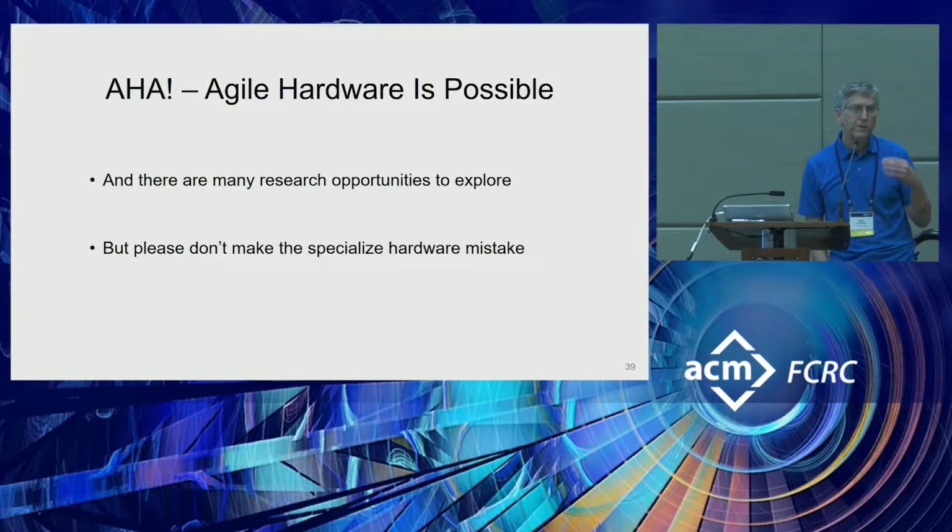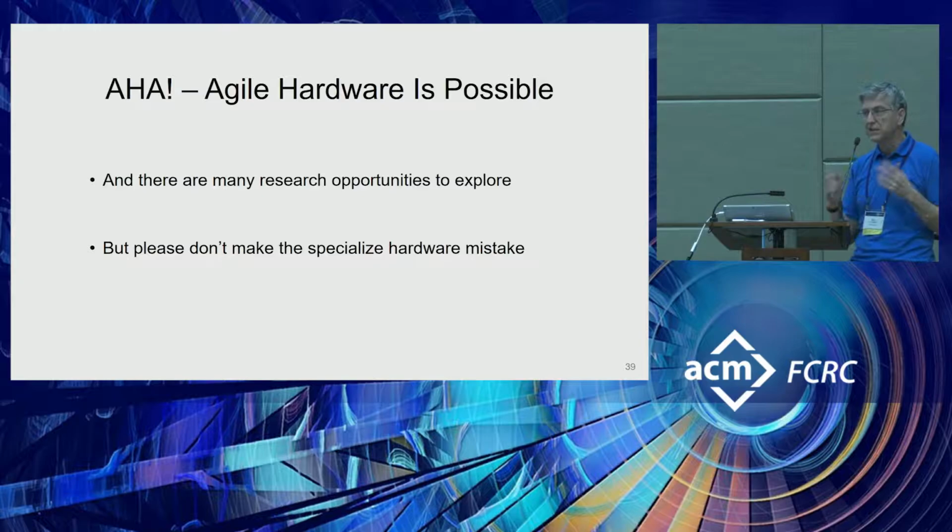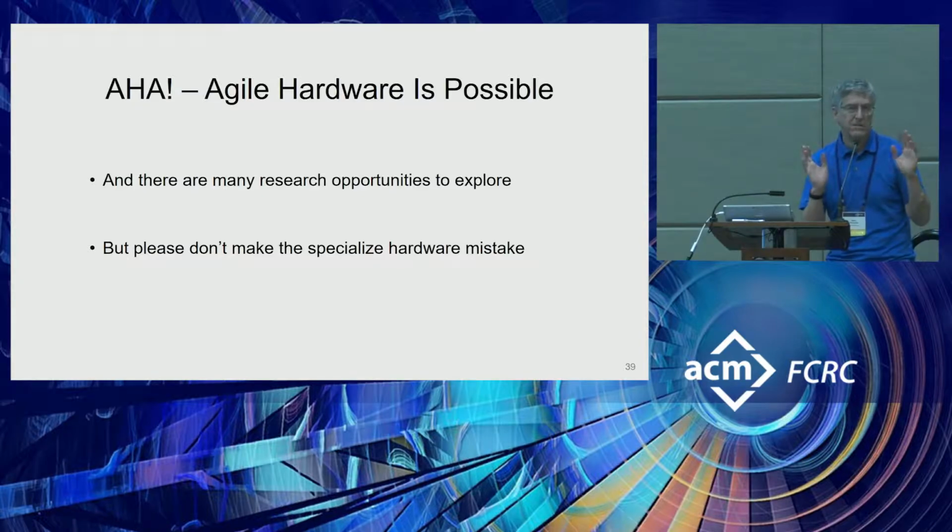If you have a formal spec, one of the problems you have, even if you have some sort of specification, is that you need to basically simulate that spec against the hardware. Well, the spec is not going to be accurate in all possible input cases because it's a spec and it doesn't actually care about things that are stupid to do. But if you put inputs in and you're basically doing random testing, you're going to run into these cases, and then it's going to mismatch, and you don't know what the problem is. So everybody in industry does what's called constrained random testing, which is they have constraints on the random test generation vectors and things like that.